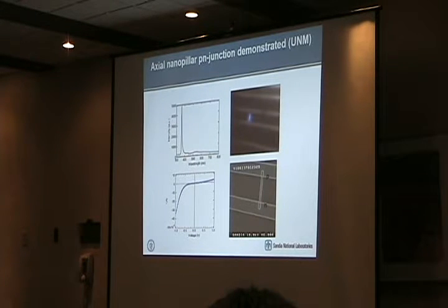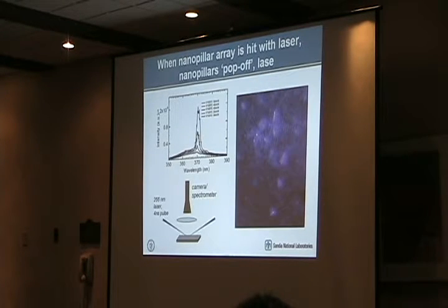One of the advantages of the nanopillars is that they can be grown under conditions that are optimum for gallium nitride growth, much higher temperature. So we shouldn't get carbon incorporation, okay? And we can start looking at lasing. Now, of course, I was very interested in looking at lasing from arrays because they can be vertical. You can think of very interesting games, for example, arranging these nanowires as a photonic crystal.